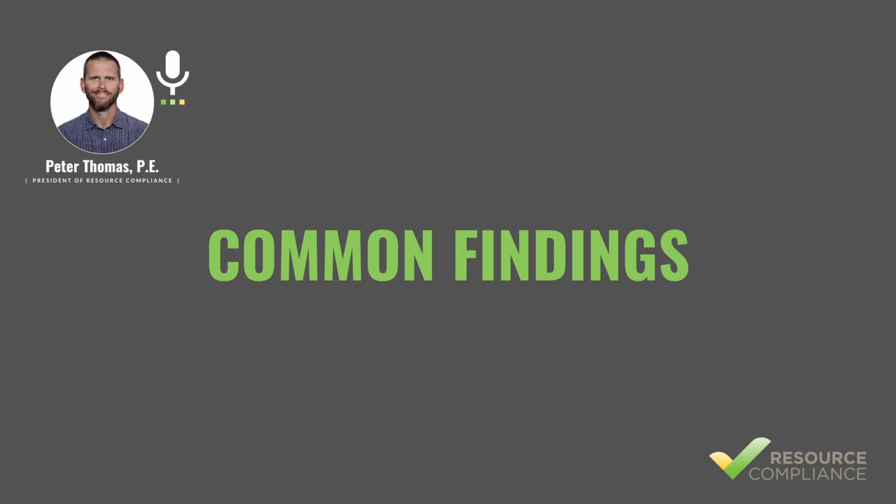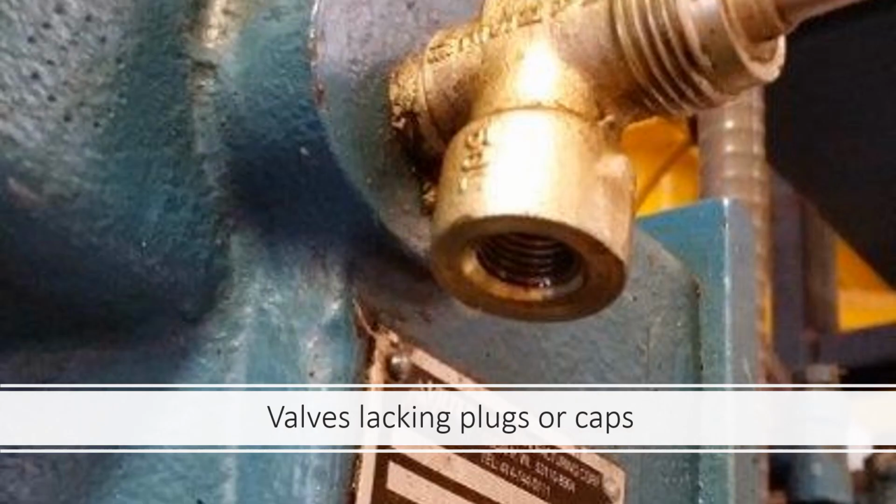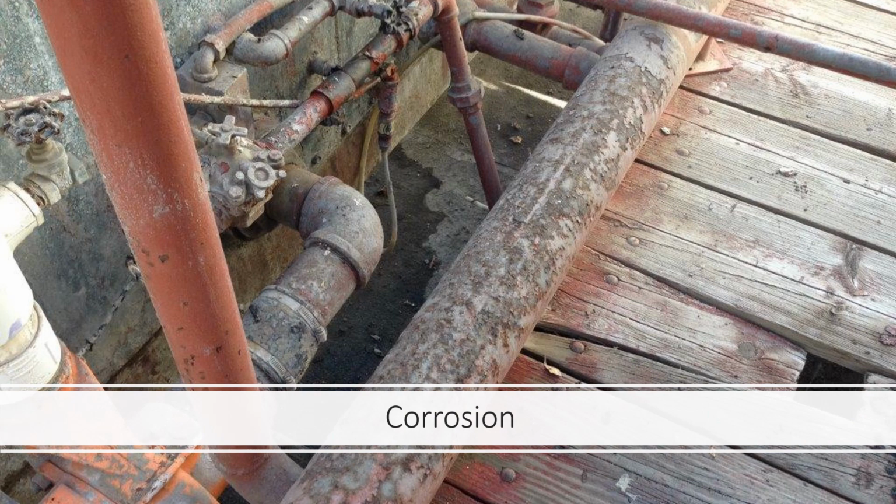We'd like to end this video by providing examples of findings that are commonly identified during a PHA. We encourage you to use this information to address any issues prior to the PHA and thus reduce the number of recommendations that are made. Common recommendations include pipe and valves that are susceptible to physical damage from being stepped on or impacted by a vehicle, service valves in the system lacking pipe plugs or caps and therefore susceptible to being inadvertently opened, pipe or equipment that has experienced excessive corrosion,